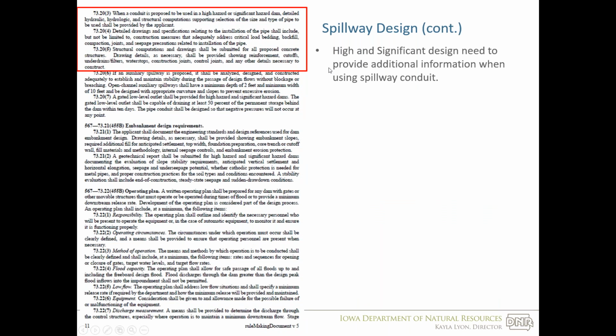And then also for the spillway design section, the high and significant hazard dams would need to provide some additional information when using spillway conduits, just to show that the pipe isn't being overloaded or is adequately designed structurally for the size of dam that it's located in.